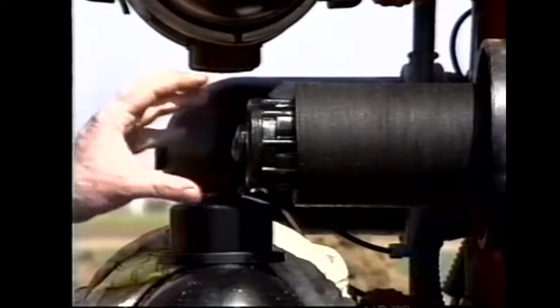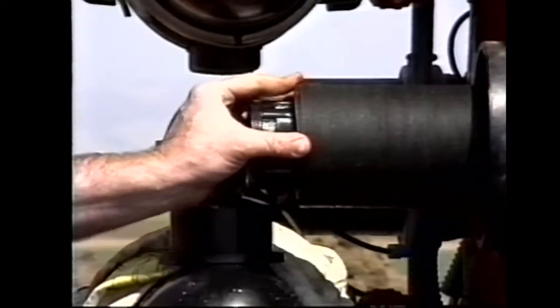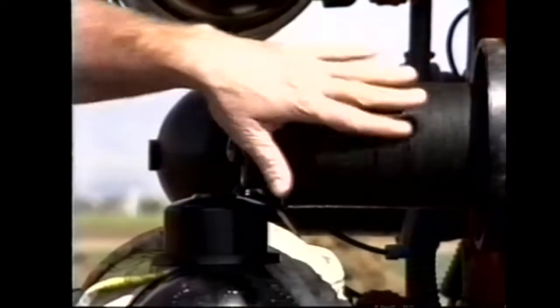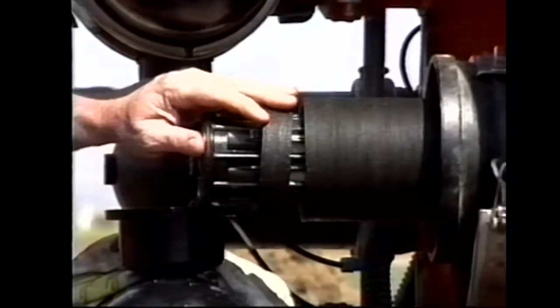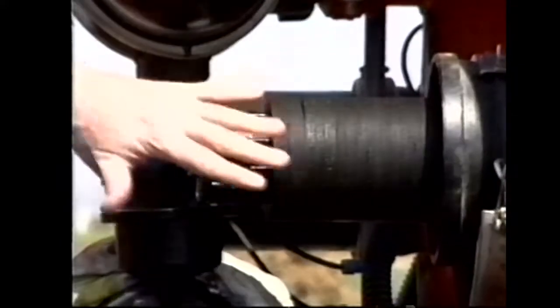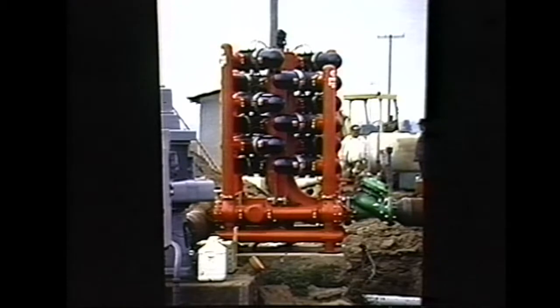During backflush, the discs are slightly separated by a special piston in each barrel, and clean water from the center pipe backflushes the discs. The discs are also spun during backflush. The spinning helps to remove any dirt from the discs. A backflush of one set of barrels requires about 20 seconds of flow, plus 10 seconds of dwell time to reset the backflush valve. Therefore, this unit requires 2 minutes for backflushing.